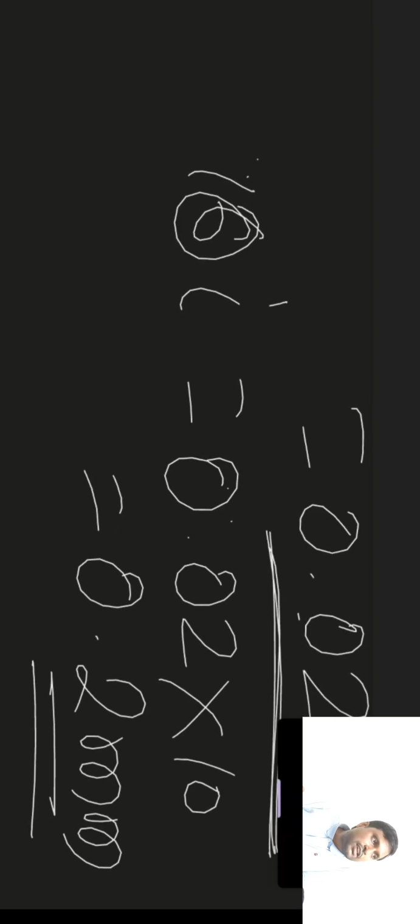So in this way we can calculate the tolerance value or the IT value, and it's easy. Then we will use this tolerance to find the limits of the shaft or the hole.